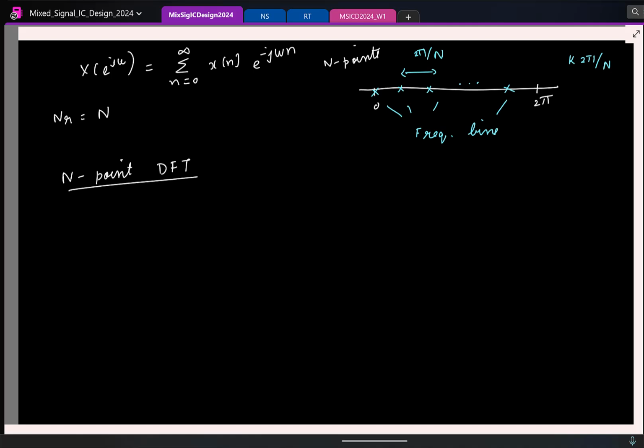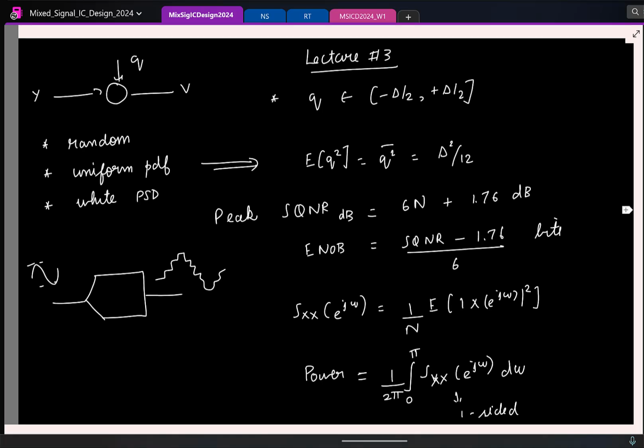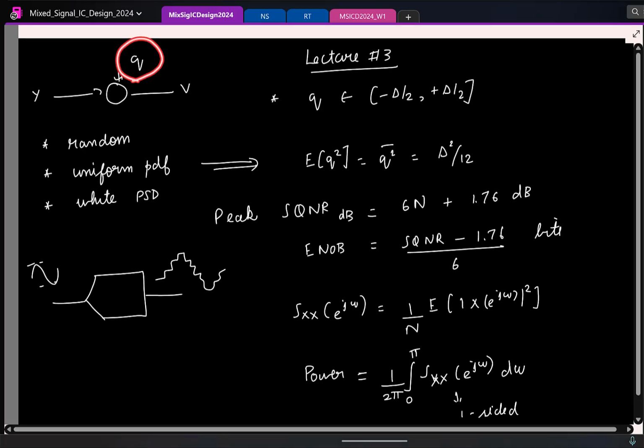One more question. Fundamentally, what is the difference between quantization error and loss? Quantization error is called quantization noise. Both are the same. But since we define quantization noise from statistical measures and error algebraically... Well, mathematically both are the same. What we are saying is this variable, we treat it as a random signal and go ahead, that's it. So don't confuse too much.